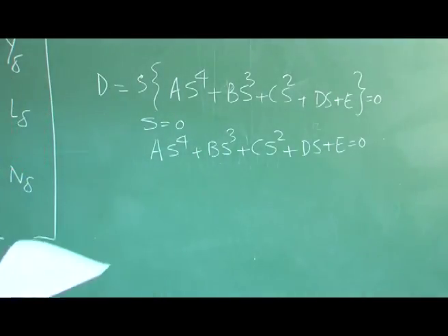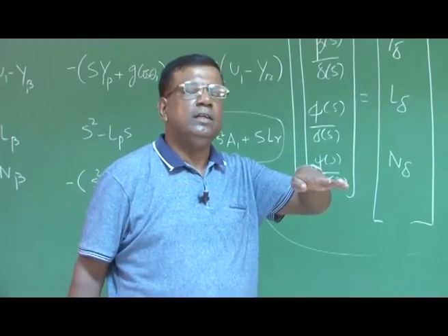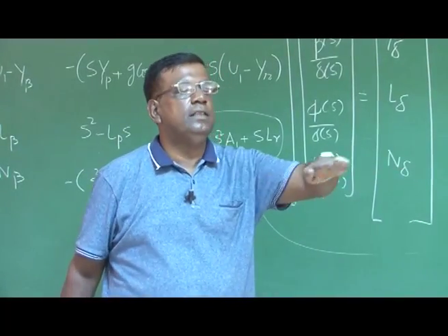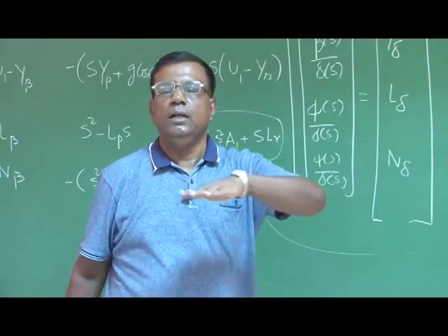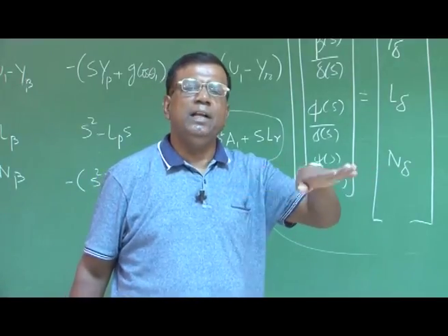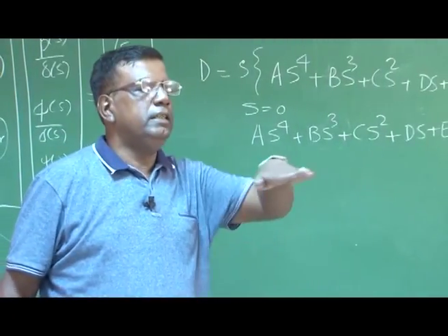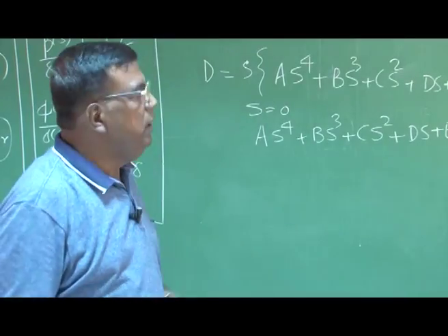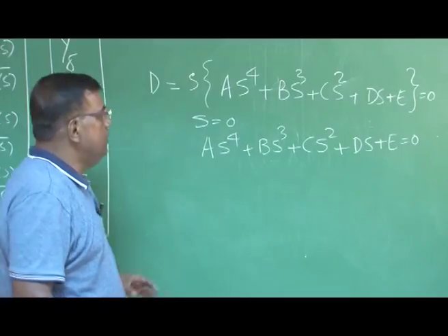S equal to 0 is the case; in the lateral directional case, it is like a neutral stability with respect to psi. See, when the airplane goes like this, aerodynamically they are neutrally stable, no change, right? No resistance, because for an airplane it is a relative airspeed. So flying at psi 2 degrees, psi 3 degrees, psi 4 degrees is the same thing. So S equal to 0 suggests that, so we neglect that, okay, we understand.